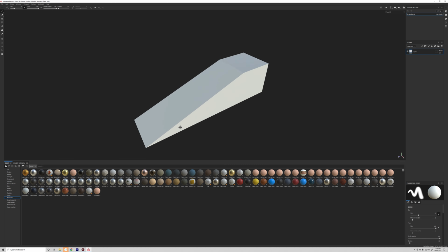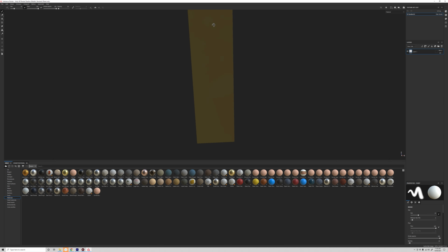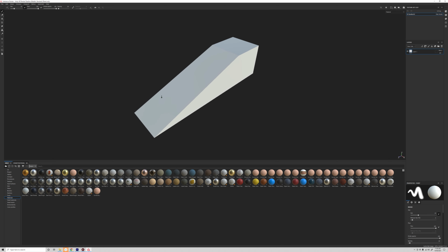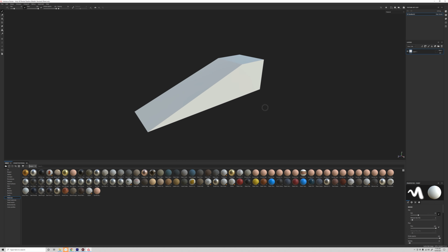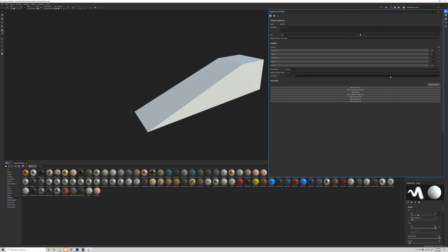And so again, we're in a 3D app. It's just like Maya, just holding down my Alt key to orbit, pan, and zoom. But before you ever start texturing inside of Substance, because I can start putting materials on, but they won't work correctly, what I need to do is bake textures, and we do that under the texture set settings. So if I click this, we can see it's this list of textures that it needs to work correctly that don't have any textures loaded, they're empty. So what I need to do is get Substance to bake them for me. So I click Bake Mesh Maps.